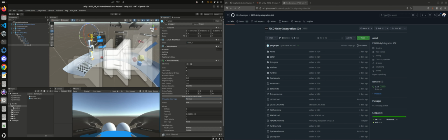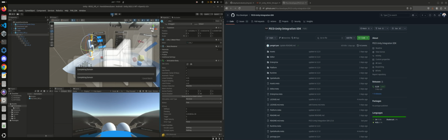And now we need to define which axis this link or this joint uses to rotate. So the first link is this, and it rotates in Y. For this reason, change here to 0 to 19 degrees. Okay, we can press play.